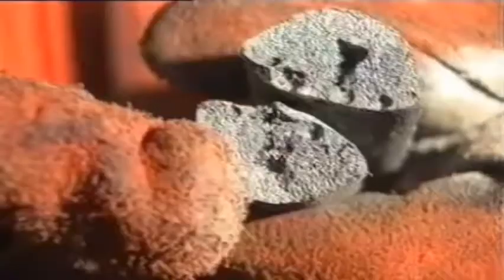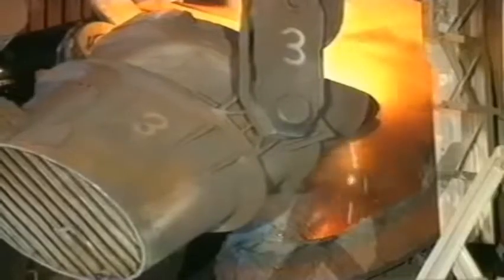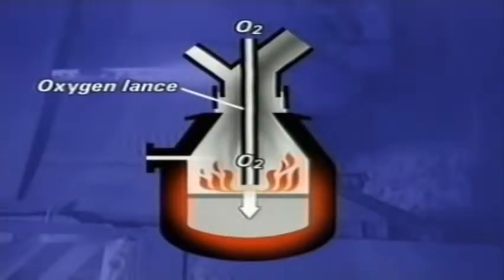Steelmaking improves the properties of iron. In the basic oxygen steelmaking process, the BOS process, a converter is partly charged with solid steel scrap. Hot metal from the blast furnace makes up 3/4 of the charge. A high-speed jet of oxygen is injected onto the molten iron, and lime, calcium oxide, is added. The oxygen converts the impurities into their oxides. The main effect is to reduce the percentage of carbon. Carbon monoxide is collected for use as a fuel.